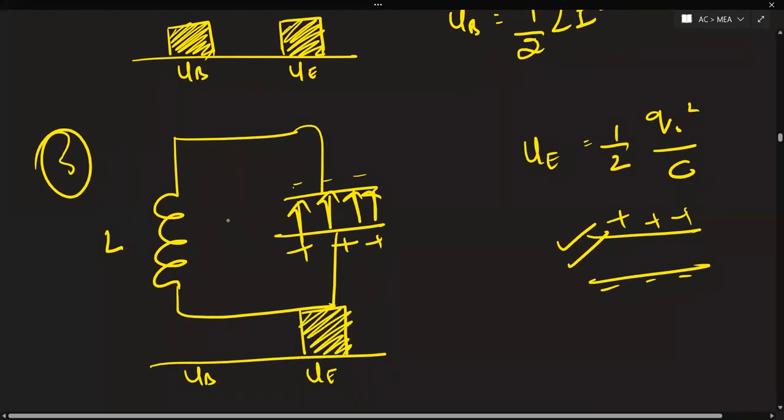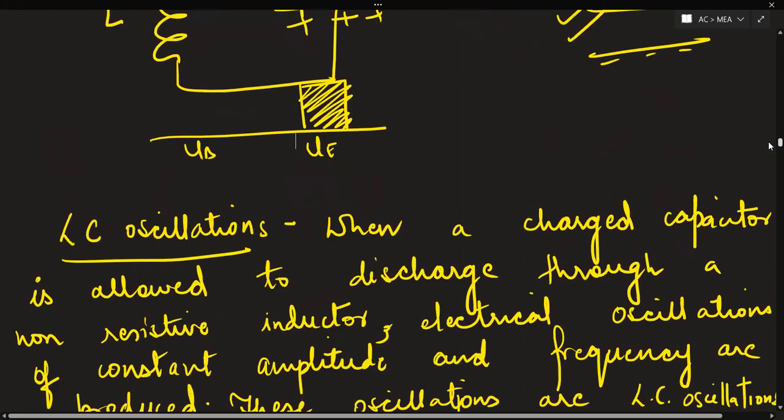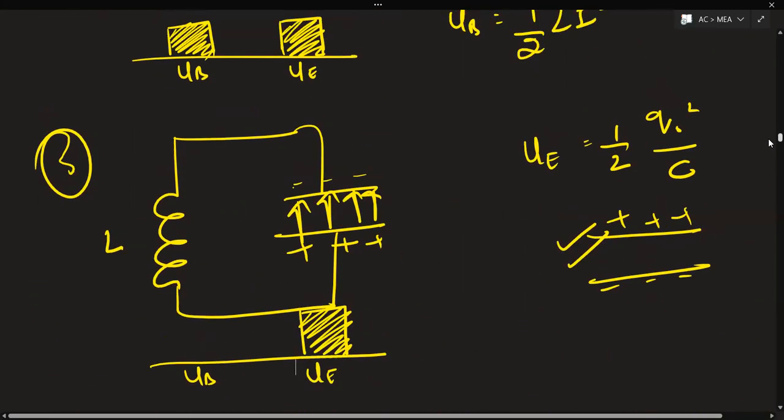Further steps will be the same as above. Discharging will begin again, the inductor will become charged, and the capacitor will become fully empty. Then when it recharges, it will shift the capacitor's polarity back. And when the polarity is achieved back, you have the initial state with which you had started. This is what is meant by LC oscillations.